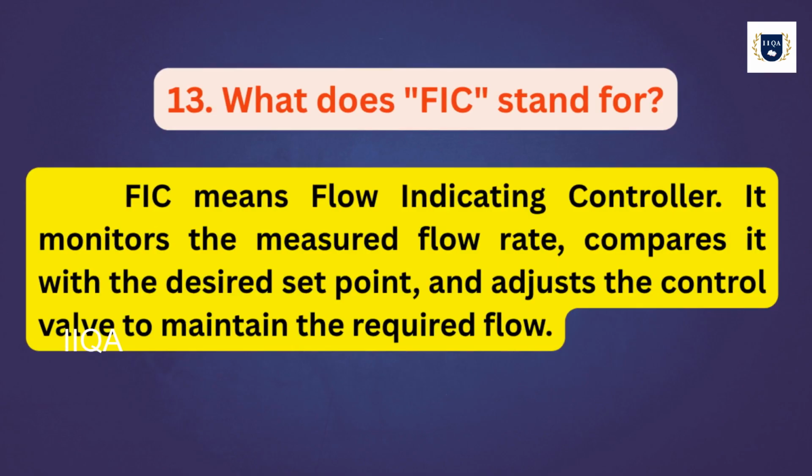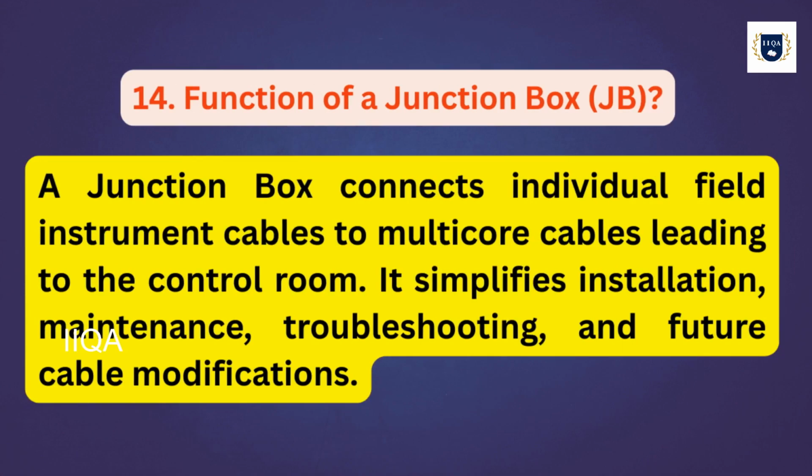What does FIC stand for? FIC means Flow Indicating Controller. It monitors the measured flow rate, compares it with the desired set point, and adjusts the control valve to maintain the required flow.